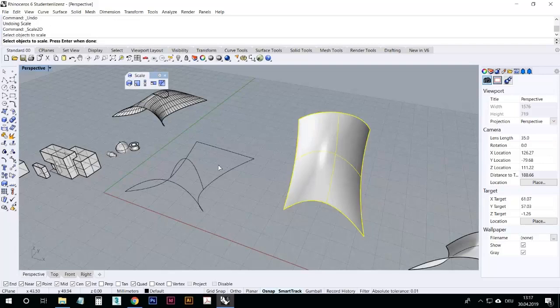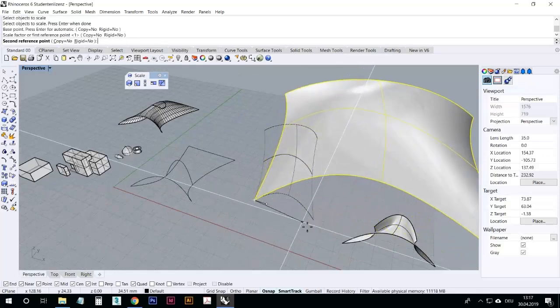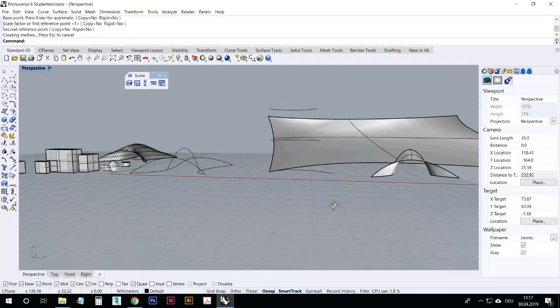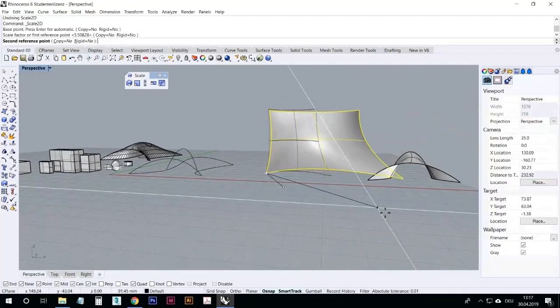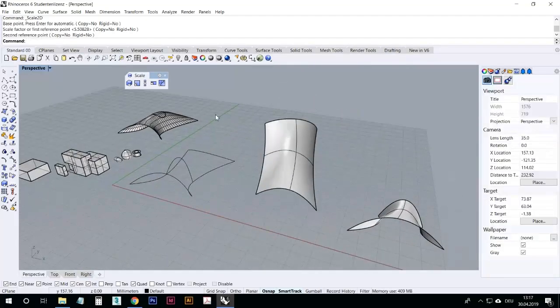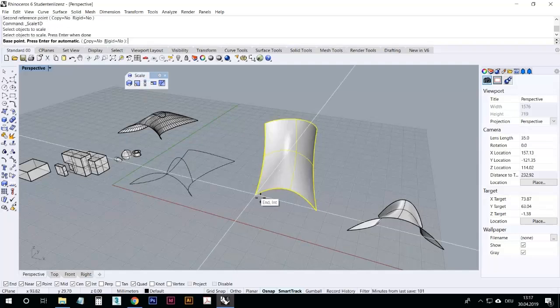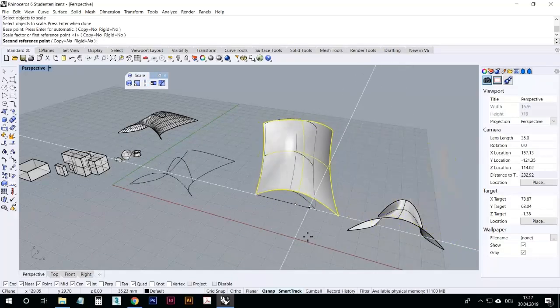So select objects to scale, enter, and then we can see something completely different. So we have a reference point of scaling, and then we start again, and you see it actually stretches. It's exactly the same size in the Z direction as before. It just scales in the XY direction. So that's a 2D scale because it only uses 2 axes, right? 3D scale is using 3 axes. So here in scale 1D, we can scale only on 1 axis. So now it stretches along the x-axis like that, not in a 2-axis system.